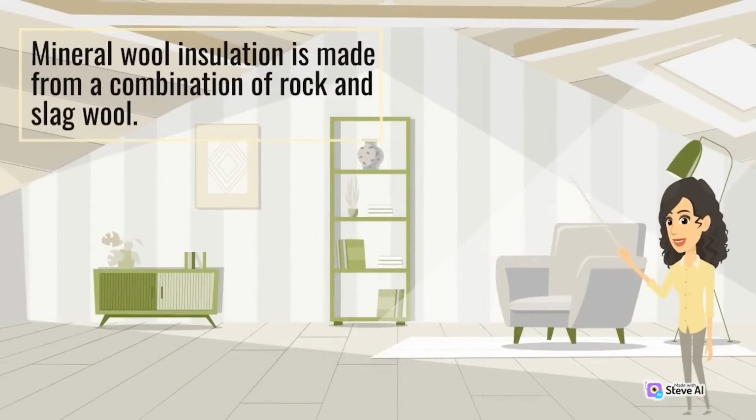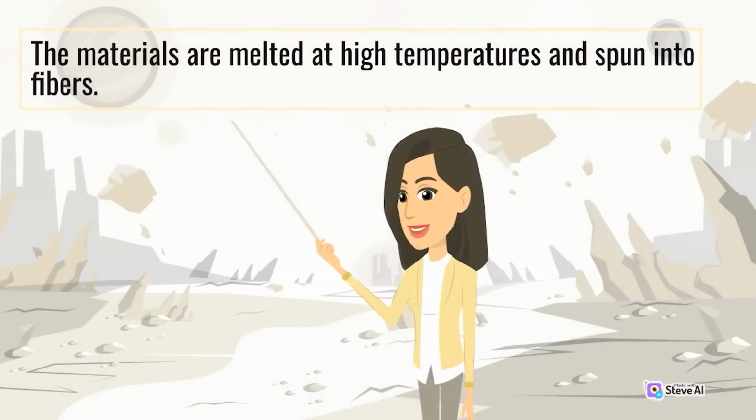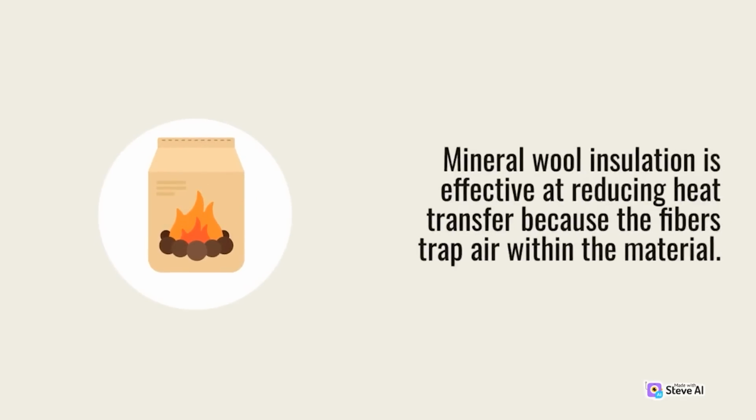Mineral wool insulation is made from a combination of rock and slag wool. The materials are melted at high temperatures and spun into fibers. The fibers are then compressed into bats or rolls and installed in a building. Mineral wool insulation is effective at reducing heat transfer because the fibers trap air within the material.